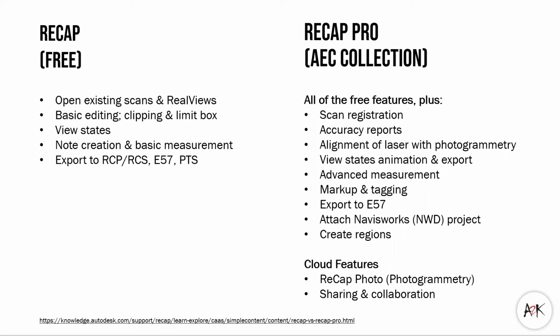ReCap Pro not only has the same viewing and exporting capabilities as the free version, but it also gives us the ability to import and go through what we call a registration process of the scans before we then export it for use in those design authoring tools. It has better viewing tools. It also has things like advanced measuring and marking up and so forth. And it also has the ability to break the scan data down into what we call scan regions.